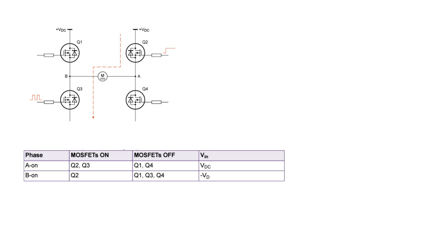If you have a MOSFET, you must use a MOSFET driver. In this circuit schema, you are seeing only the MOSFET. However, we have a circuit here, the MOSFET driver. So you can buy the MOSFET and the MOSFET driver from the market. Okay, if you want to drive a MOSFET or IGBT, you must use a driver.